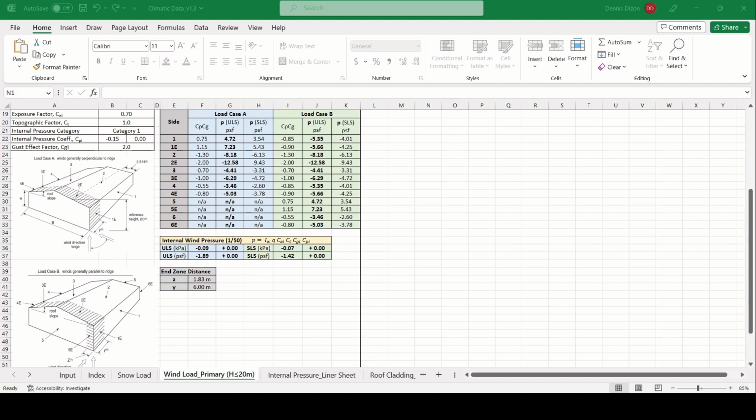But when you design the shear wall itself, or you analyze the anchor for your trusses to the template, then that's the time you will include this value here. But for lateral, of course, it is perpendicular to the plane of your load application. That is not included in the analysis, because the summation of forces is along x, but this suction is along y, so you will not include that one.